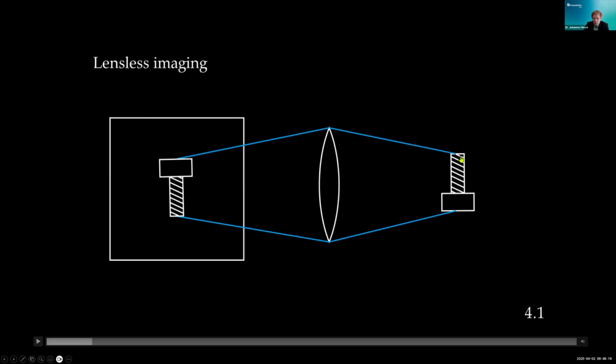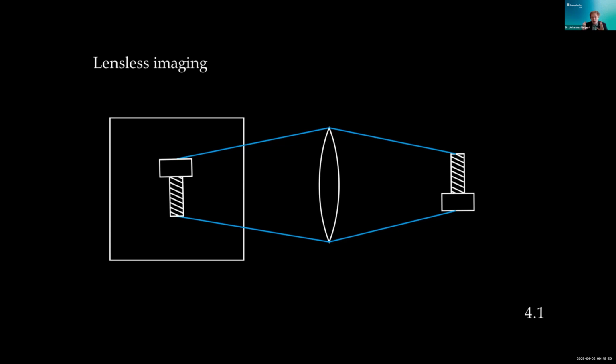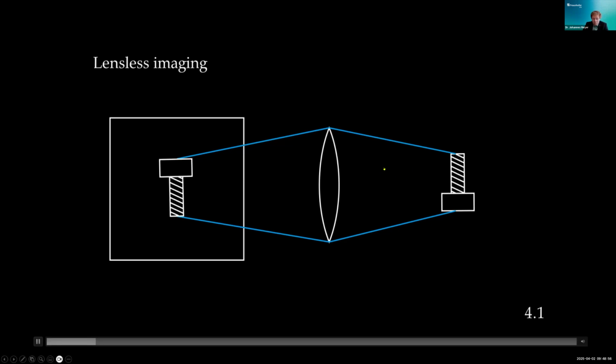And what you typically do is you select the corresponding lens system, the corresponding objective lens, to get a clear and sharp image of your screw on your sensor, and then you continue with all the development of the image processing. Now, unfortunately, in reality, the objective lens is not, as I've drawn it here, a single lens that you put somewhere in your system, but it's typically, especially if you think about telecentric lenses, those are really huge objects consisting of a lot of optical components, what makes them, of course, kind of expensive.